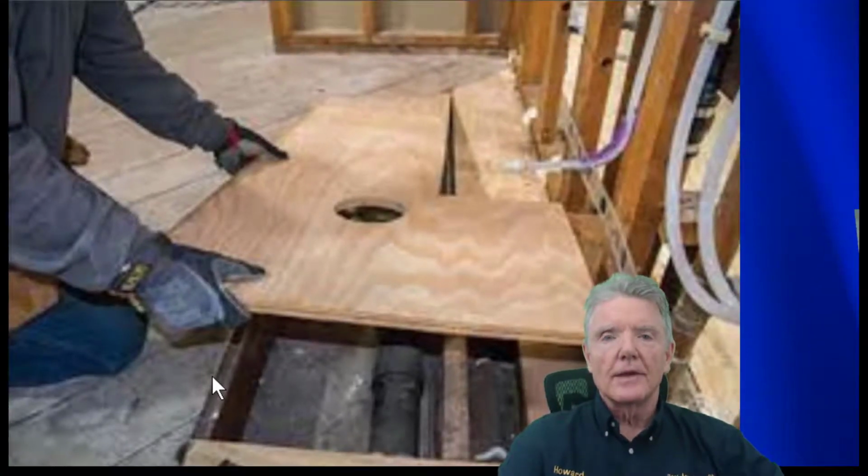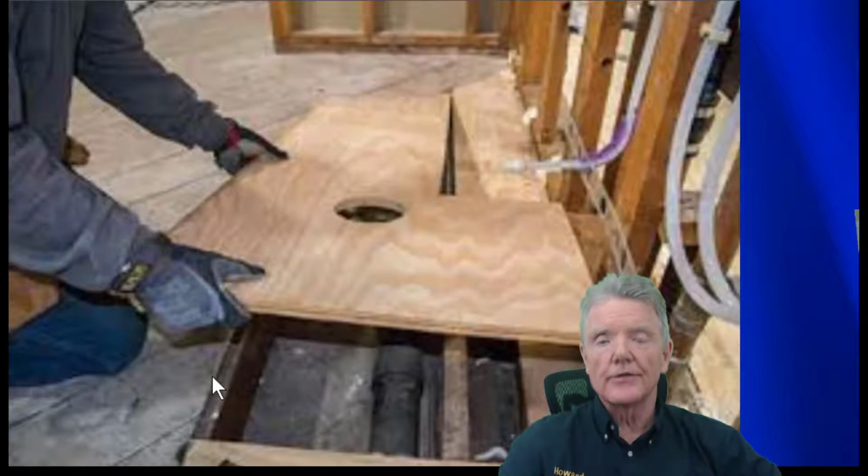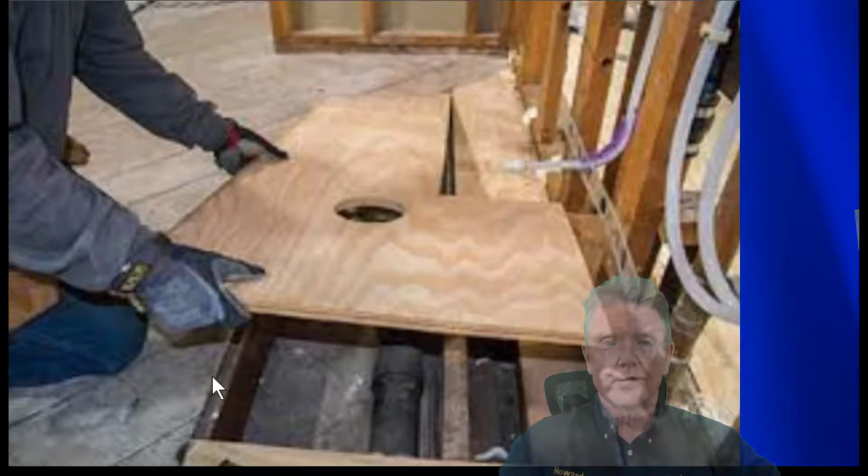And then when he puts this piece of plywood in, he might put 1 or 2 nails or 3 nails. He's not going to worry about earthquake forces. He just wants this piece of plywood to sit on this board, and then he can put in his plumbing and whatever he's going to do at that point, new floor. So what's happened is he's really seriously compromised the ability of this house to resist earthquakes.